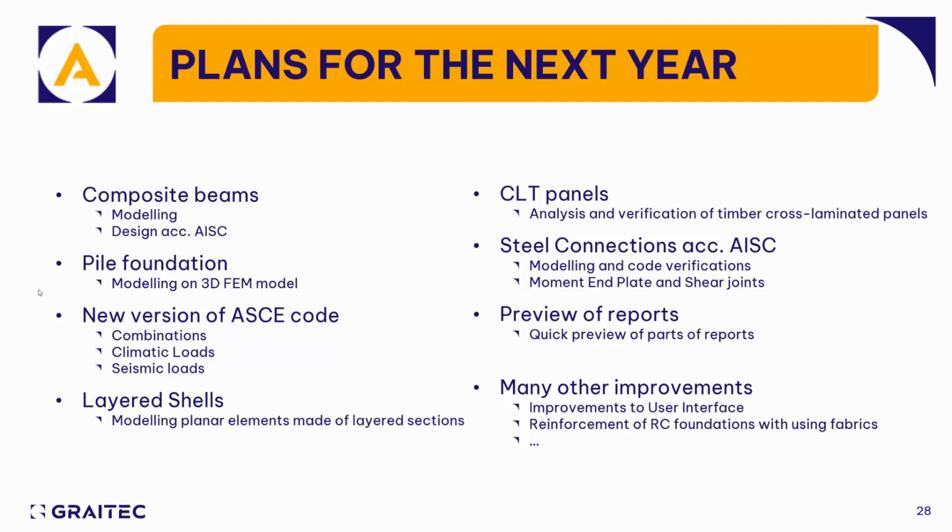Another very important new feature here is layered shells. It's going to help the modeling of very specific planar elements. You can define different layers for your planar elements, which will include all of the stiffnesses and the correct behavior of your layered shells using this new feature. Analysis and verification of CLT panels is also under work. We are also working to have steel connections modeling and design in Advanced Design, again based on ASC codes. Right now we are working on moment and shear connections.